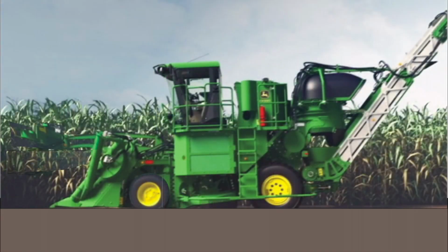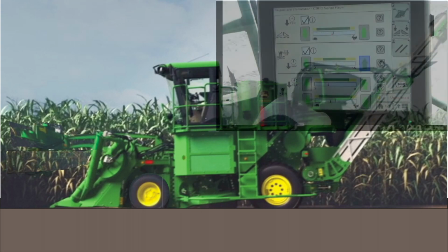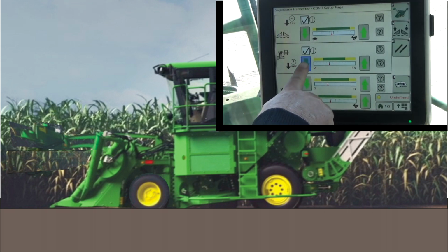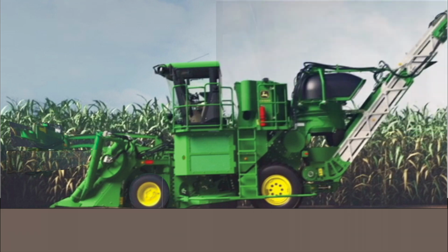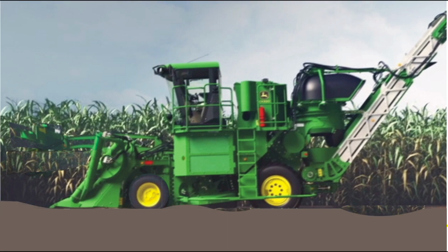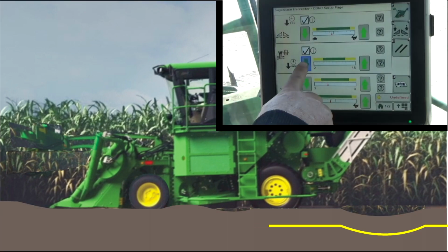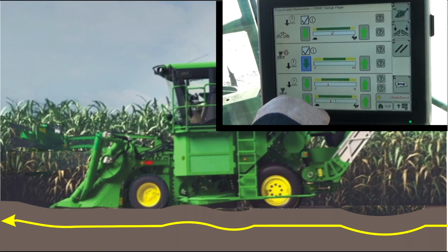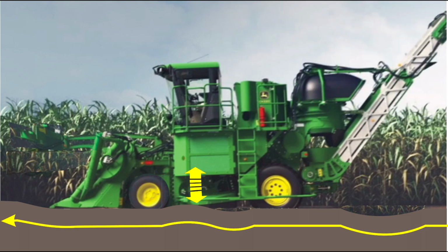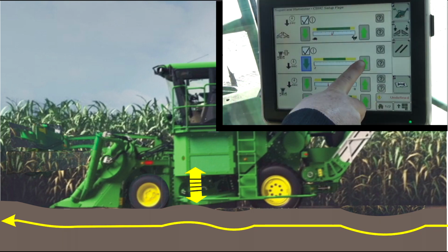In a field with a very consistent contour, with few surface variations and pressure lifts, a low setting may be practical and would allow the base cutter to quickly return to its set position, maintaining a relatively short and consistent stubble. If the contour is uneven, a low time setting would result in constant, undesirable base cutter height changes.